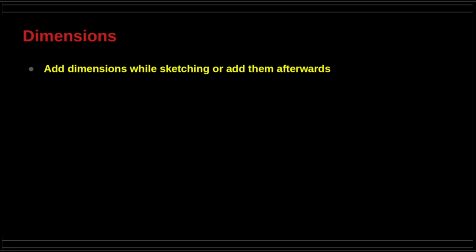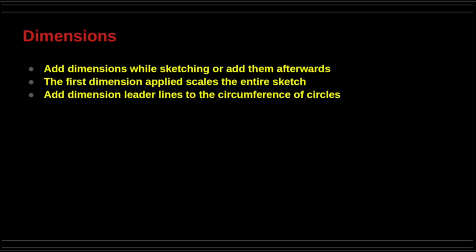You can add dimensions while sketching or add them afterwards. The first dimension applied scales the entire sketch. Add dimension leader lines to the circumference of the circles.